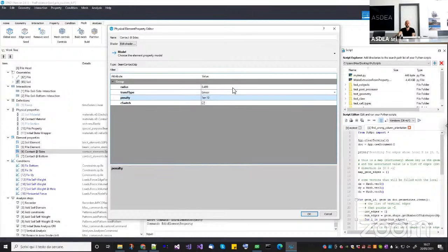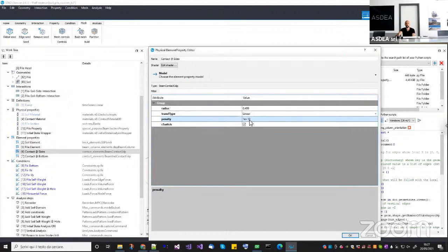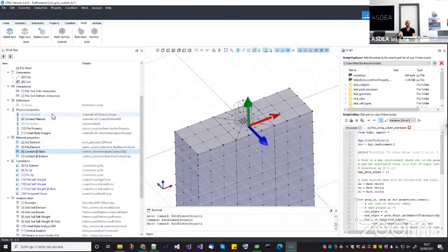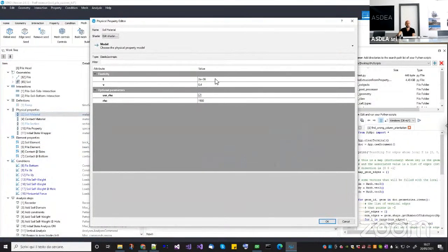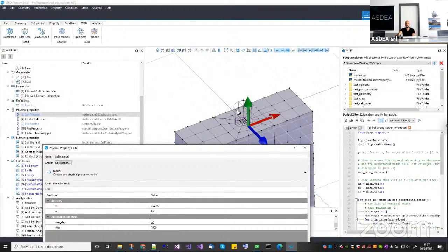Okay, so how do you calibrate this number? Well, what I do actually is to estimate the stiffness that I have in my model, and I put a couple of orders of magnitude more than that. So for example, in my model, I have a Young modulus of 10 to the power of 6, okay? So this Young modulus will be multiplied by the volume or the area or the length, whatever it is, of the element. Now these elements, since I'm modeling in meters, they have a characteristic length of 1 meter.